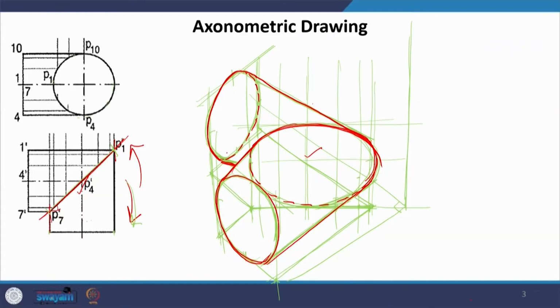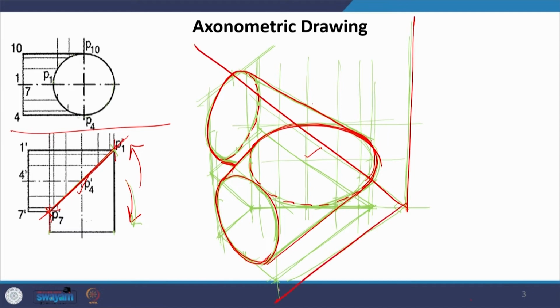Because very simply if you see, when we rotate it, this is going to be seen in its actual dimension. It is going to become parallel if the reference plane remains the same. So, we just rotated it, but actually the reference plane is now this. This is our reference plane. And now, if you see, you can actually see how these two cylinders are coming together and joining.